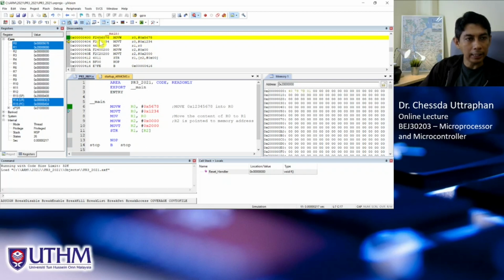And what is this? This is the machine code. It means that the mov w instruction is encoded to this value. This is 32 bit, f2 4 5 6 0 7 8. So this is the encoding for this. The machine code, the one that the microprocessor understands, is this. This is the human programming language, but this one is what the microprocessor knows what to do.